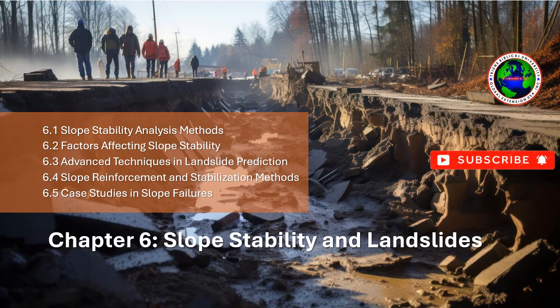Lessons learned. Proper management and monitoring of waste piles and slurry heaps are essential to prevent failures. Adequate drainage systems are critical in preventing saturation and instability in waste materials. Careful consideration of site selection and long-term stability of stockpiles or waste heaps is essential.